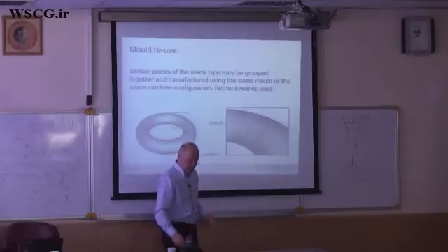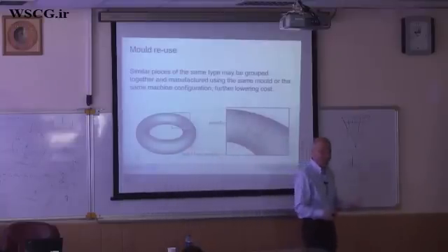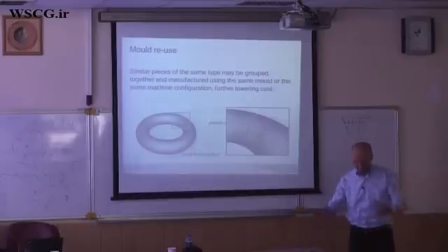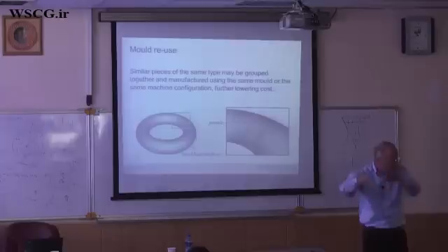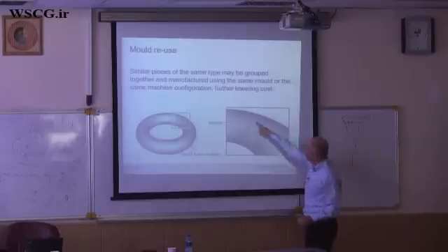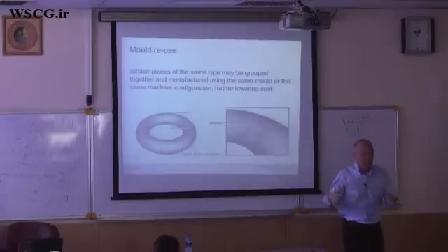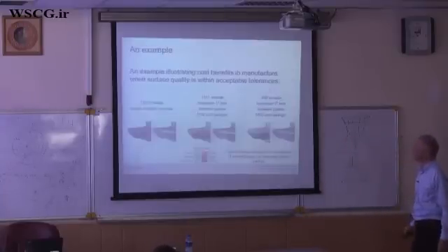And certainly, I may produce different patches with the same mold, but just putting some material in a different way onto the mold, like glass, you have to heat it up, put it onto the mold, or cut the boundary out in a different way, like here. So with the same mold, you may reuse it for different panels, and this mold reuse was incorporated in this optimization.